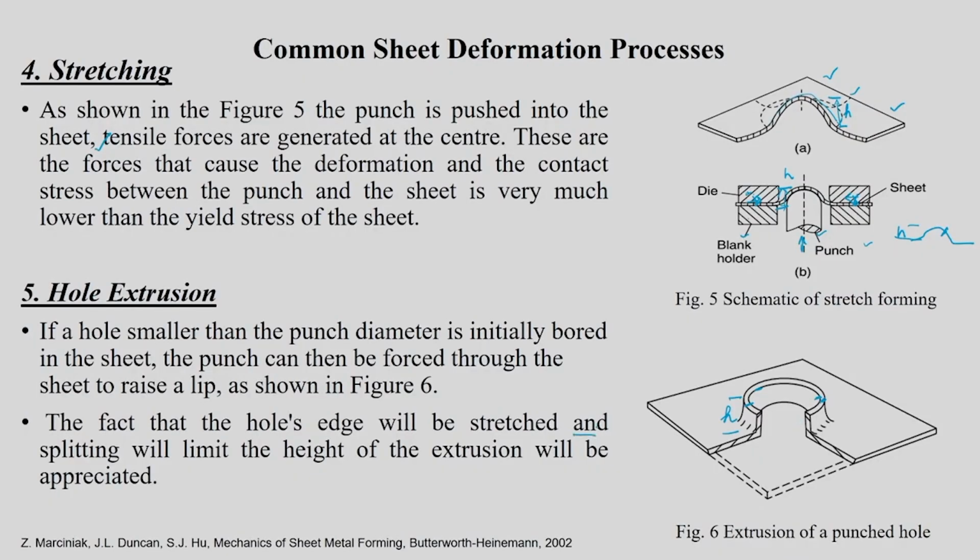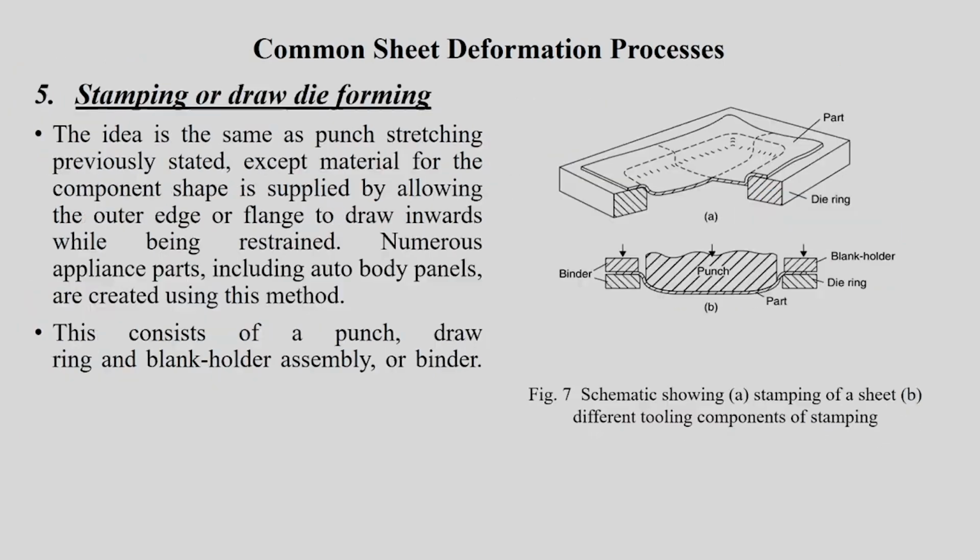So, I have just written here that the splitting will limit the height of extrusion. The larger the height, the better, but at the same time you should be able to make the whole stretching operation without any problem. That means a fracture should not happen at the edge region.